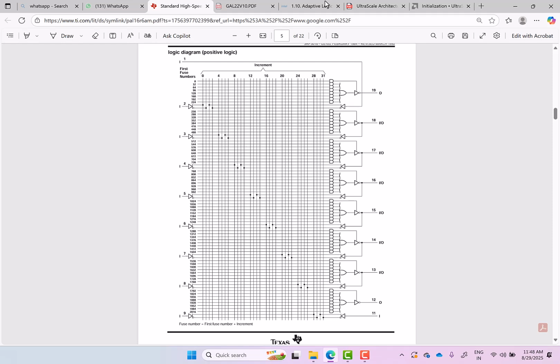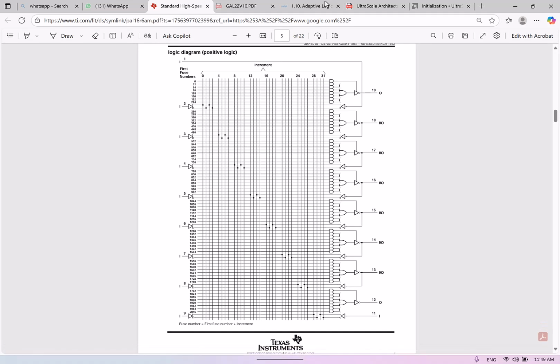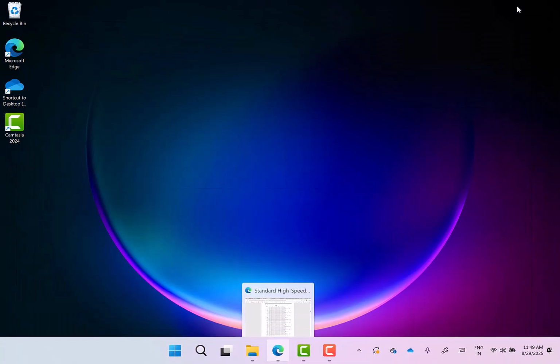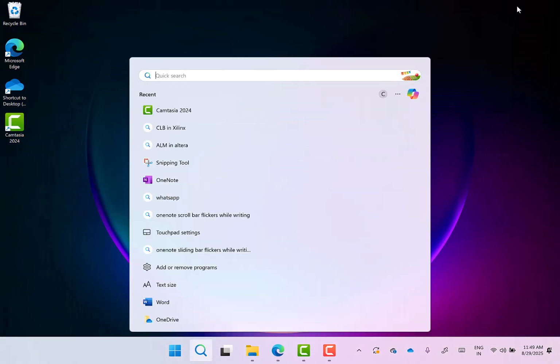Alright, so now again, back to the business idea. If I wanted to implement a combinational circuit, now I can either get a PAL, PLA, or use a read-only memory, right? What is missing? Combinational circuit part, it is done, right? But are digital circuits only limited to combinational circuits? No, right? We want some sort of flip-flops also into this array, right? So with that, we come to other types of programmable logic devices.